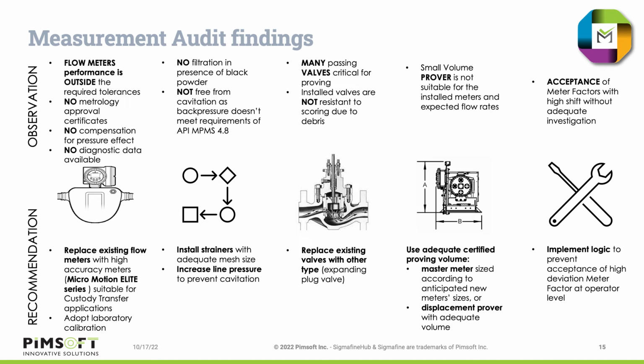There are a few common findings for liquid measurement that we have observed in many locations. Among those common observations is that the flow meter is not suitable for the specific application. It could be that the technology is not suitable for the fluid properties, for example, turbine meters for high viscosity oil, or the meter performance in terms of repeatability and reproducibility is not as per the applicable standards and regulations. New meters with performance suitable for custody transfer application are recommended.